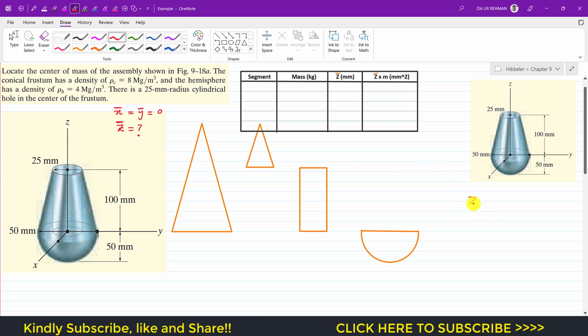So from the principle of moments, we can write that z bar will be equal to the summation of z tilde times m divided by the total mass. So now what we need to do is find the product of z tilde times mass for these 4 segments, and then find the total mass, and then we need to apply this equation, then we will be able to find that z bar.